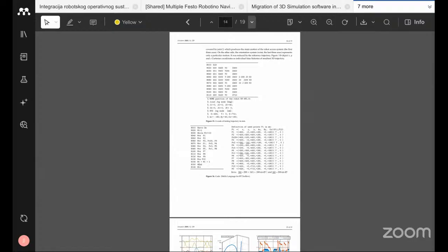This one is showing the Melfa language programming. Melfa language is for the Mitsubishi robot. For example, servo on. Servo on means to enable the servo. Then PR1, PR2, these are reference points. So P1, P2, P3, P4, P5, like that, different points.